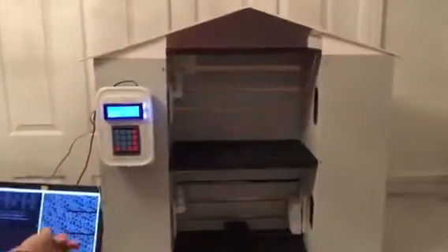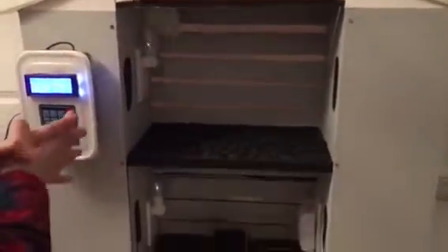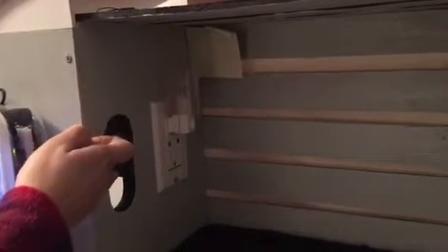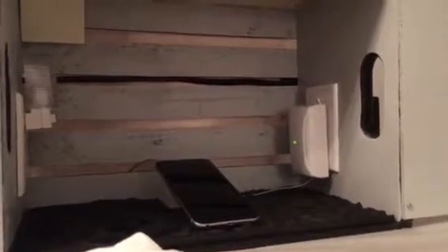Inside of our home, what we have are two smart receptacles, which are X10 receptacles. We have two digital motion sensors that are covered because once motion is detected, the X10 outlets are turned on and the lights will come on. For the X10 receptacles, the top one is controlled, the bottom one is always hot. Communication gets done by this X10 modem. The X10 modem is plugged into a normal receptacle as you would have in your home. The communication is through the power lines to the X10 smart receptacles, and the whole system is wired up as your home would be.